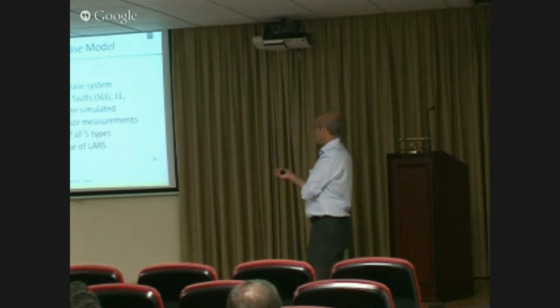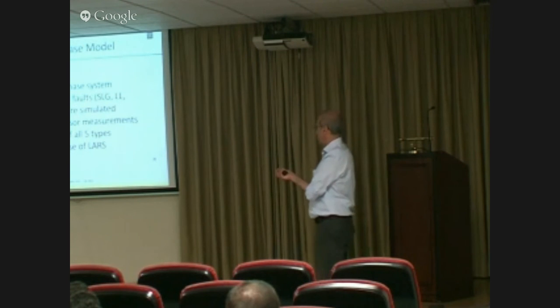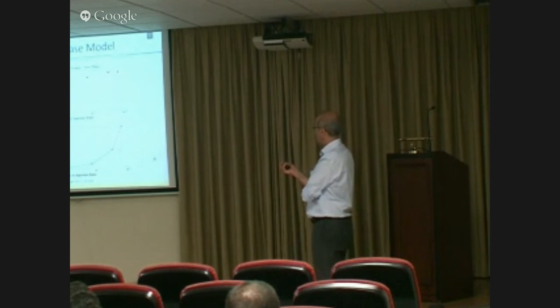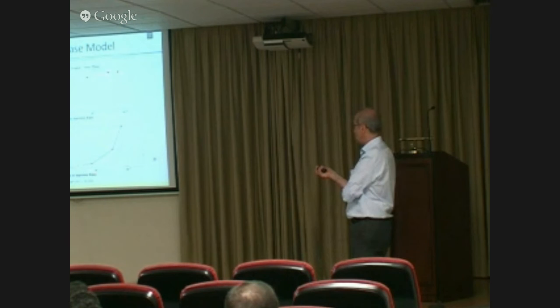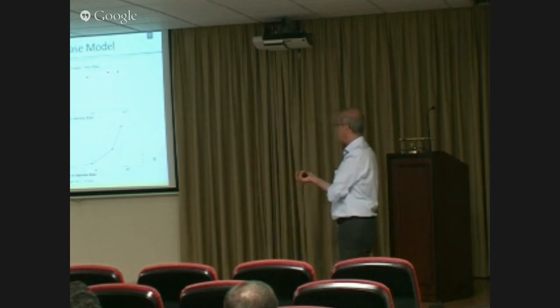And we tried it also for the three-phase model, which is this. We take the 30-bus system and turned it into a three-phase equivalent system, and we applied all sorts of different types of faults with 16 voltage phasor measurements in this case. And we got similar results. Again, here, the number of iterations grow with noise, and the success rate drops. Actually, this is not too bad, even though it looks worse than the previous one, but this is a small number. Yet still we see this drop in performance as you increase the noise.